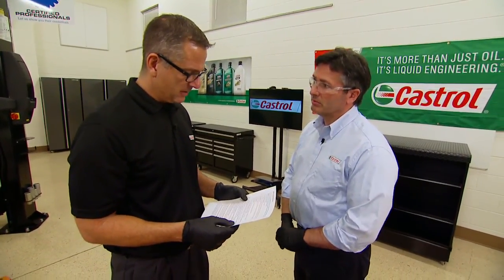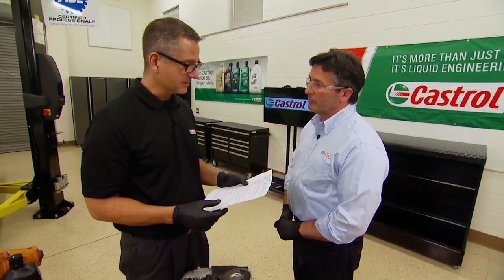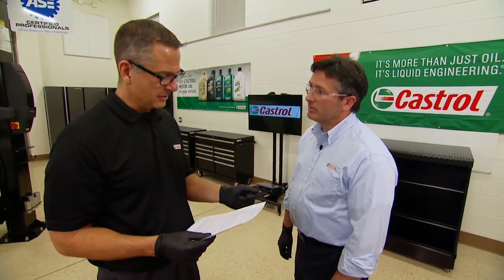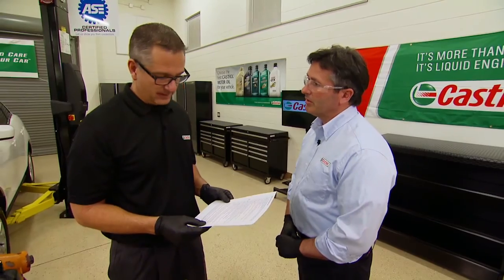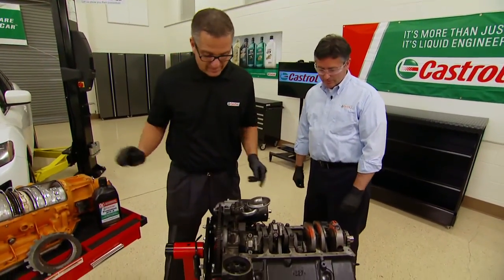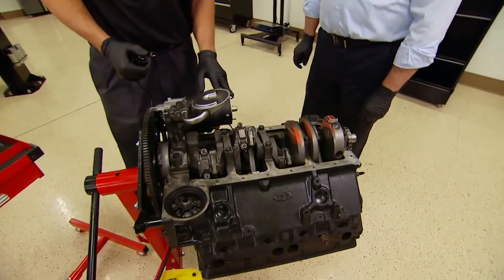I see. What about also there's anti-wear agents? That sounds pretty self-explanatory. Sure, anti-wear agents are exactly as they say. They help prevent against wear in highly loaded areas inside the engine. Friction modifiers help make slippery surfaces so that parts move more easily against each other, and this helps with fuel economy. And I know there's also anti-foaming agents. Yes, John, the role of the anti-foam is to prevent formation of bubbles in the engine oil. We don't want air bubbles getting into the bearing area. They just don't provide very good lubrication like engine oil does. All right, and we could show that right here actually. The actual foam agents, I know a little bit about that because the crankshaft spins around.